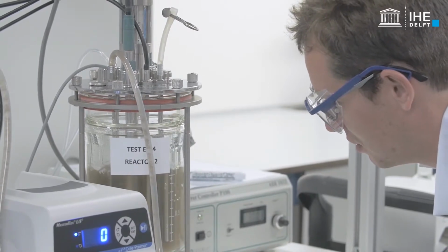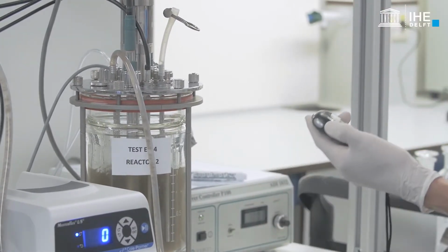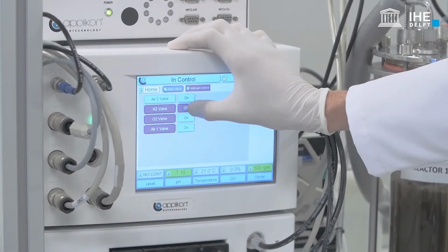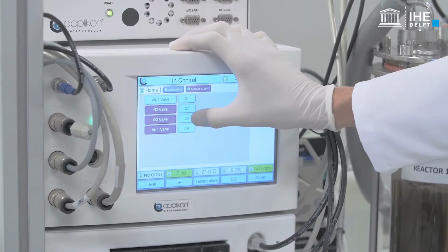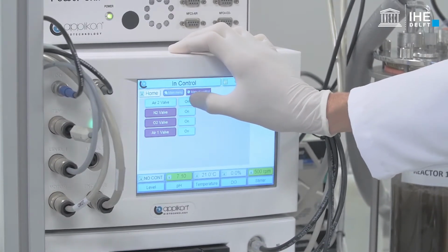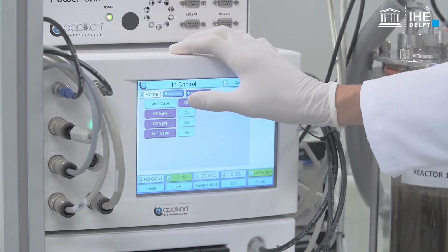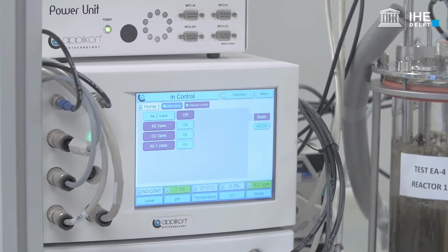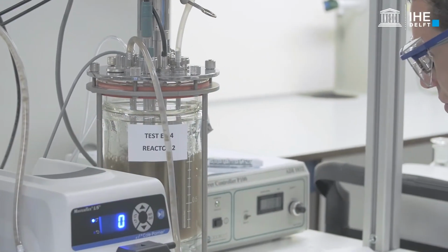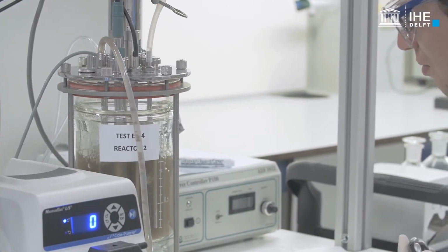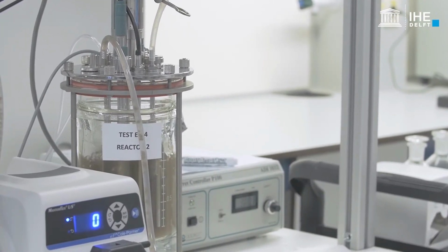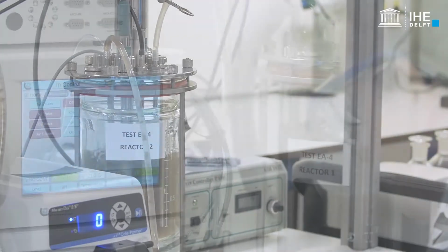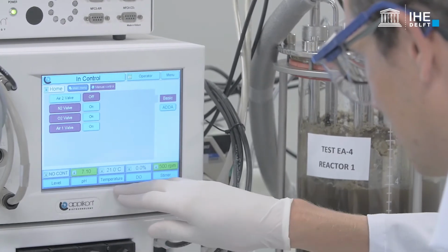To carry out simultaneously the anoxic phase in Reactor 1 and the aerobic phase in Reactor 2, start up the air supply to Reactor 2 2.5 minutes after the nitrate solution is added to Reactor 1. This will create a delay of 2.5 minutes in Reactor 2 with regard to Reactor 1 and facilitate the simultaneous sampling of both reactors. Confirm that the operating conditions are stable and get ready to start the simultaneous sampling of both reactors.